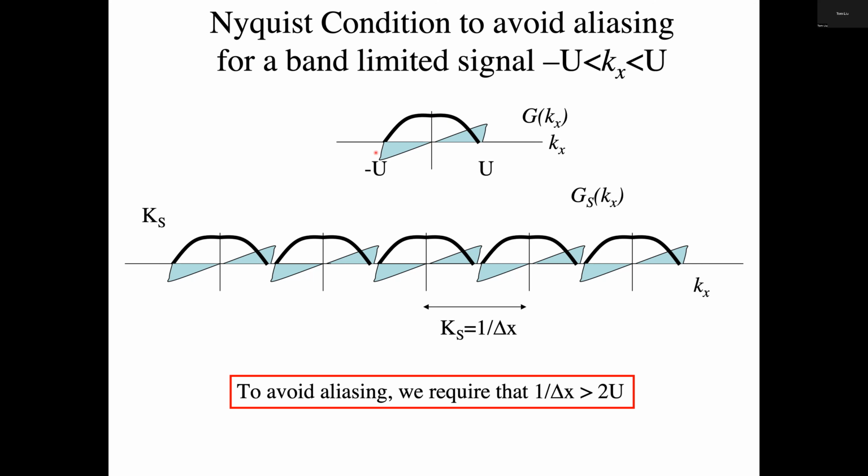So this is the band limit of our signal. If the band limit is such that we're at this point, and our sampling comb puts the replicants of our function at 2 times this band limit, then these functions just don't overlap. So when I ask what is the value of my Fourier transform at this point, I don't have to worry about leakage of signal from one of these replicants here because I know it's gone, right?